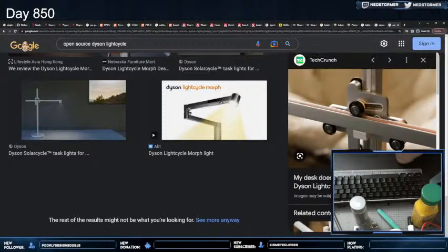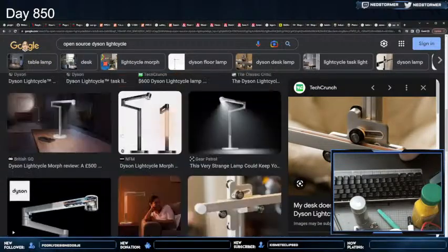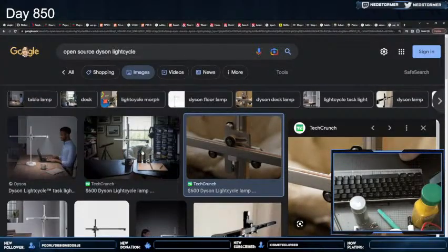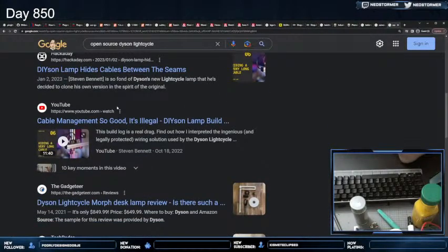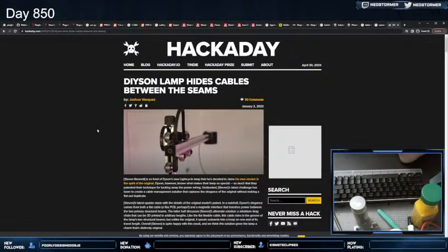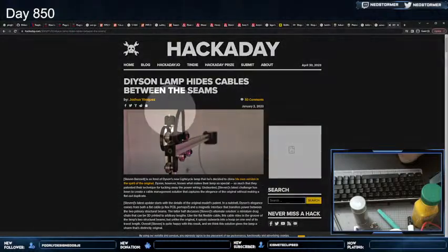I think what I'd rather do is put in a cylindrical bearing on the rod and then have a tensioner on there so you can reduce how quickly it can move. Yeah, this is the open source project.